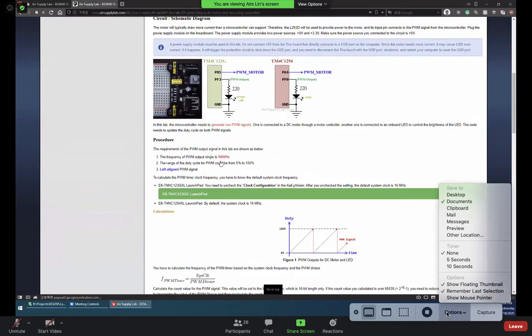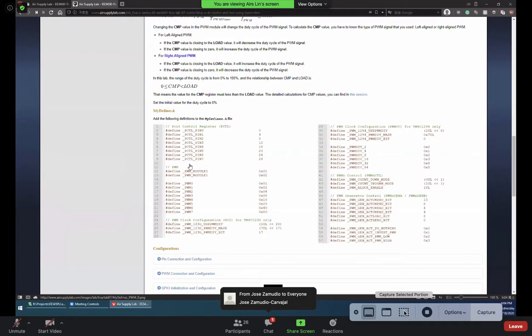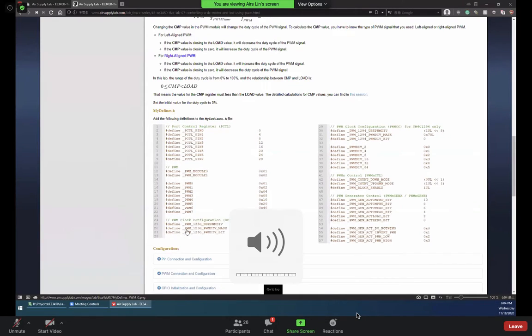Okay, so the Lab 7 here, the PWM definition. This one, I sent all the email to all of you guys last night about my definition for PWM. So for the PWM DIV mask, previously I gave you the 3. No, 3 is incorrect. It should be the 7 because we use 3 bits. We use 3 bits for the PWM divider.